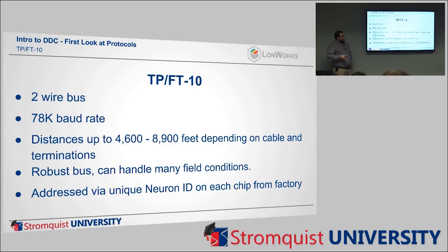One disadvantage to that is if I have a controller that goes bad and I need to change it out, I can't just put a new controller in there and set it to the same address. I've got to go to whatever is managing the system and say, this controller is now this address instead of this address.